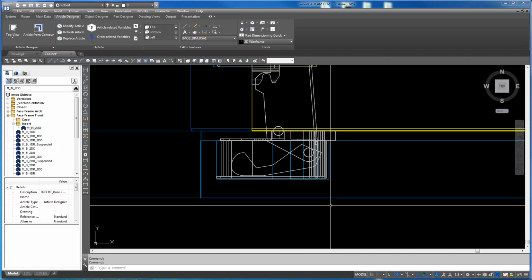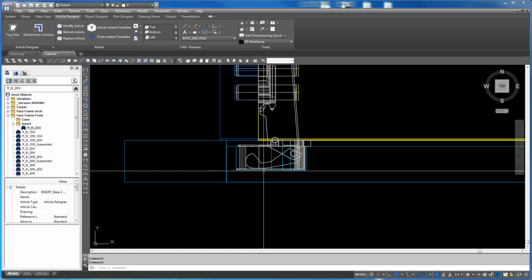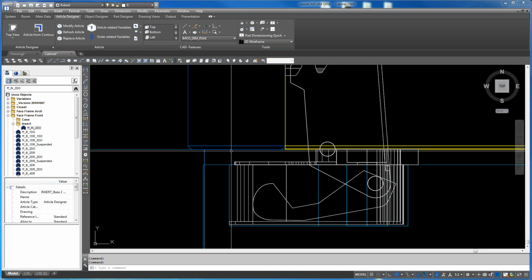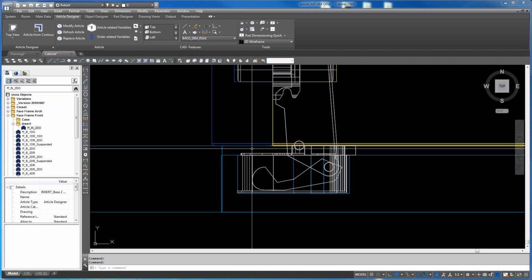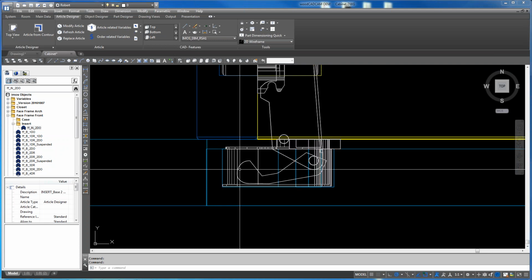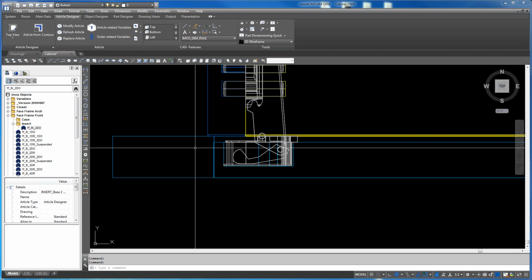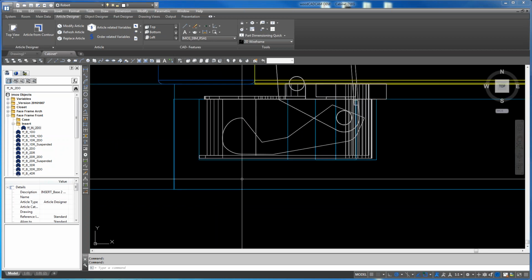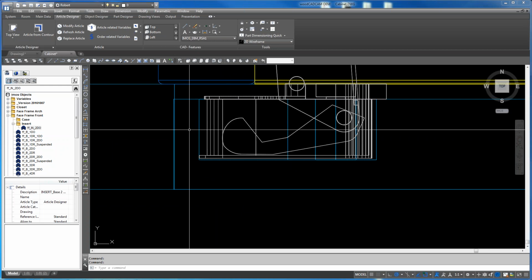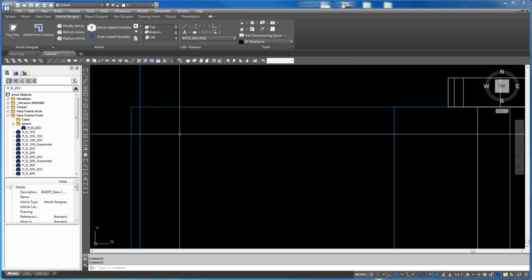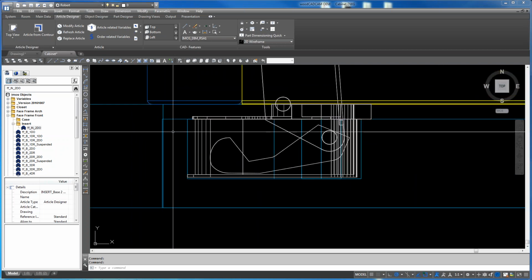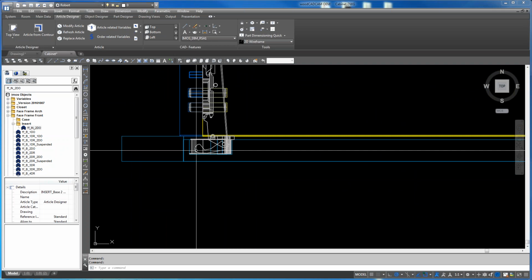So if you see my screen, usually what we would do is have a face frame attached to our box. Either the box would be exposed by 5/8 or full 3/4. Let's say we keep it as I have it right now. First of all, I'm not sure if I attached this frame the proper way. And two, if I can't modify this door, obviously I need to have a 3/32 gap around my frame. Right now the door is even wider than the frame is. So that's my problem.